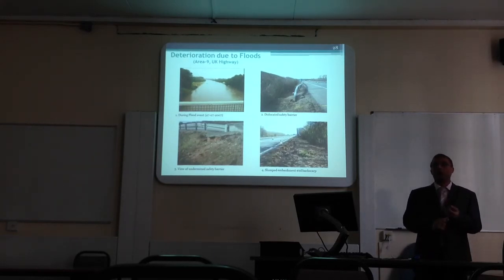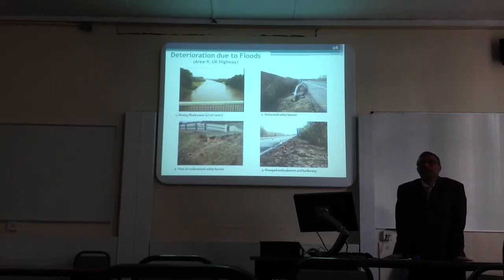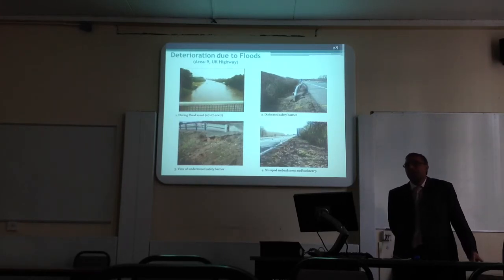And we looked at burrowing, erosion failure. Hang on, let me just finish. We talked about bearing capacity failure, we talked about settlement, and now erosion. And one gets the impression we're looking at the macro scale, as a whole embankment going down. But what other things might happen if the embankment floods? Remember, it's carrying a road.